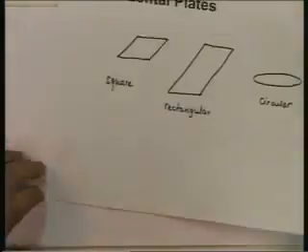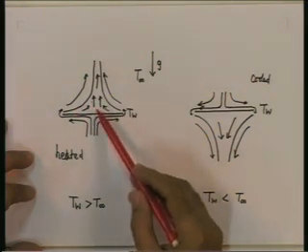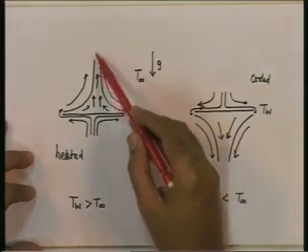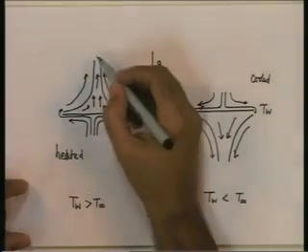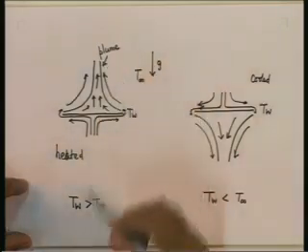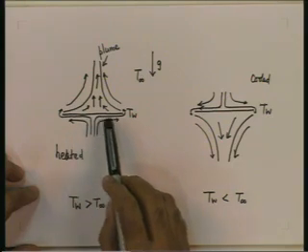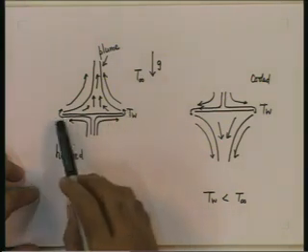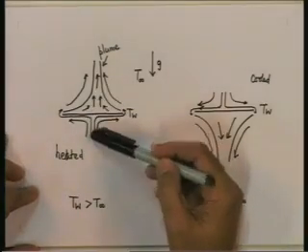We also considered a typical horizontal surface, and we said that if the surface is hot, then the fluid over it will try to rise in the form of a plume, whereas the fluid below it will tend to stick to the surface, but will try to escape from the sides. The flow pattern will be different on the top surface and on the bottom surface.